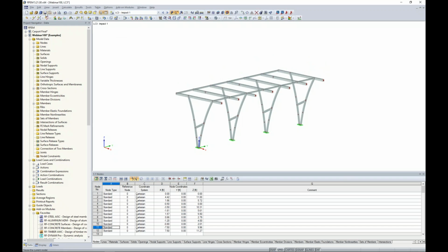Now, for impact load, this comes from the ASCE 7-2016 and specifically section 4.5.3 for vehicle barrier systems. The code tells us that for impact loads, we should consider a 6 kip load applied anywhere between 1 foot 4 inches to 2 feet 3 inches above the floor. So for this application, I want to consider an impact load on my center columns here.